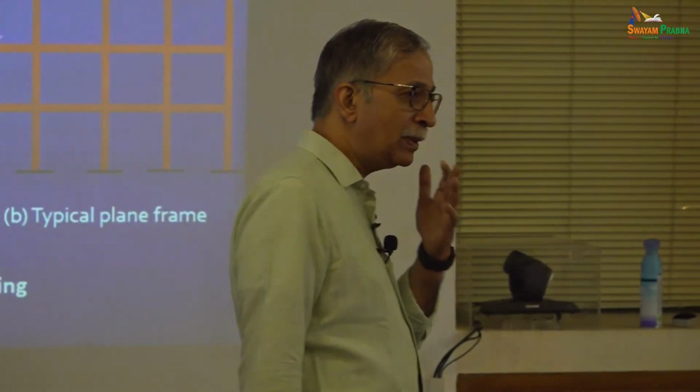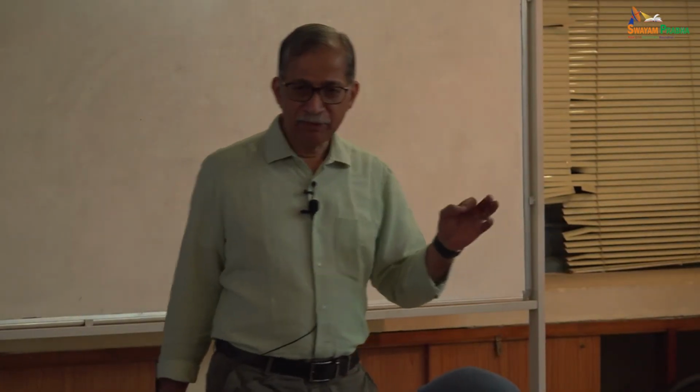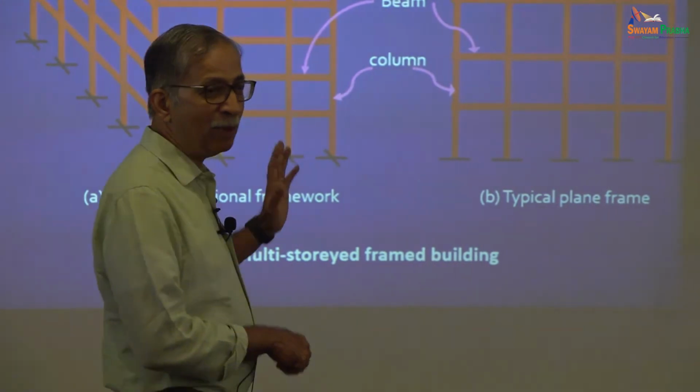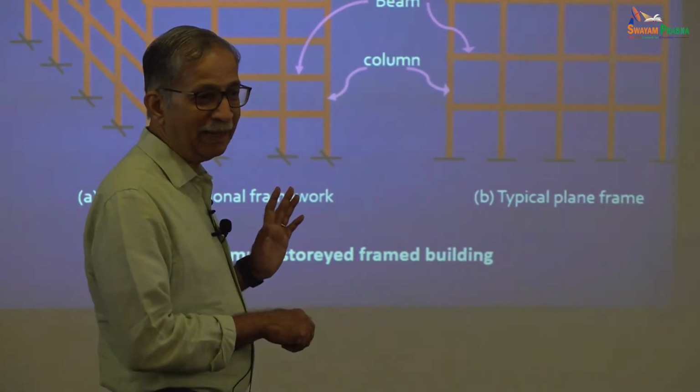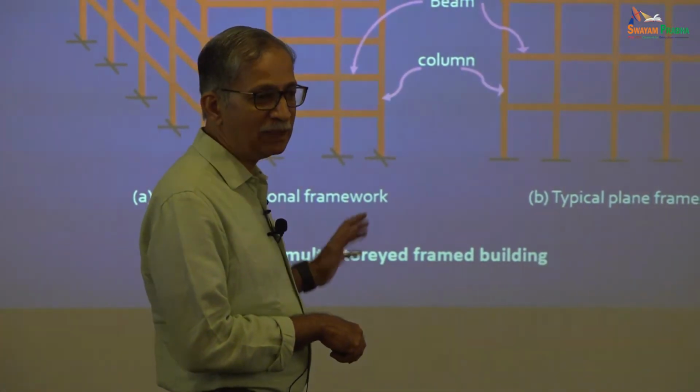The reason is all these elements are subjected to bending moment, shear force and axial force, right? Though you are imagining that the column is subject to axial compression. No, there may be some loading situations where the column is subjected to axial tension. Can you give me an example? Yeah, but those are, you assume lateral loads, that's one loading condition, but you're ignoring gravity loads there, and then you might get uplift, but usually the gravity loads will compensate and still put in compression.